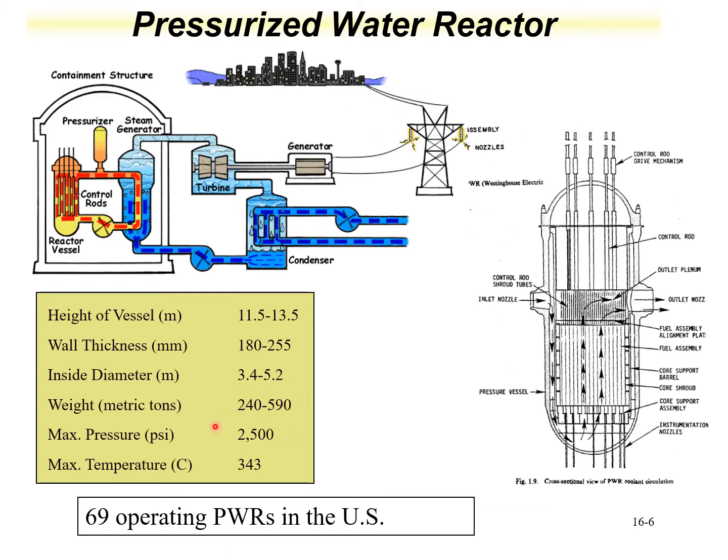As the name implies, a pressurized water reactor has a maximum pressure of 2,500 psi and a maximum operating temperature of around 350 degrees C. A schematic of this reactor, very similar to other power reactor designs, is shown here, where the heat is generated in the reactor vessel. The coolant from the reactor travels to a loop where a secondary loop of, in this case, water, transfers the heat and produces the steam. This steam turns a turbine. The water condenses and continues to loop around.